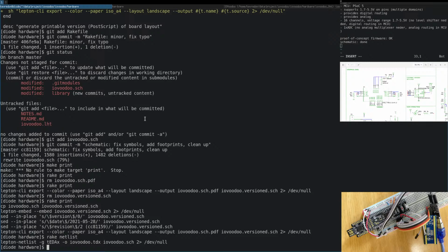And that's my flow here. I have a completely different program for the board layout than for the schematic capture. And what is very important is that both of them can communicate, or at least you can put the components from the schematic to the board layout. And this is done with an interchangeable, standard format, like whenever you finish the board layout, you send some Gerbers to the one who produces the board.